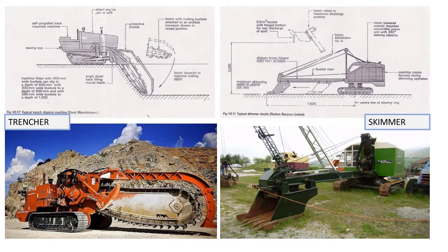Next plant is trencher. A chain trencher cuts with a digging chain or belt that is driven around the rounded metal frame or boom. It resembles a giant chainsaw. This type of trencher can also cut narrow and deep trenches. The angle of the boom can be adjusted to control the depth of the cut. To cut a trench, the boom is held at a fixed angle while the machine creeps slowly.